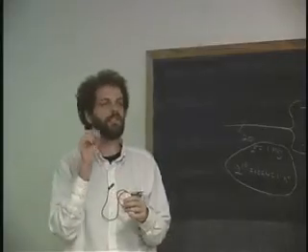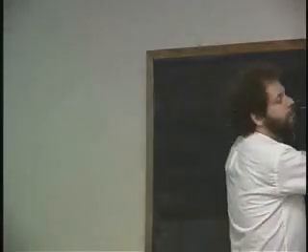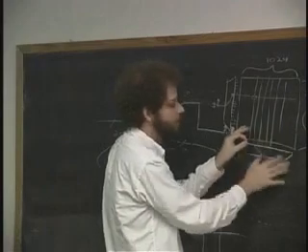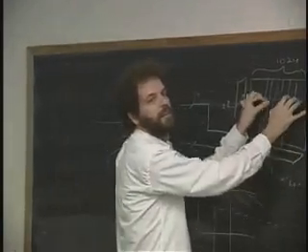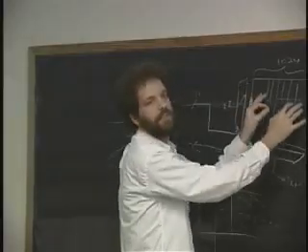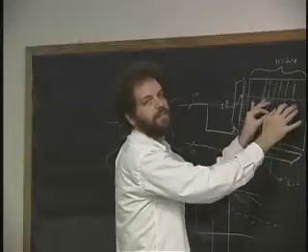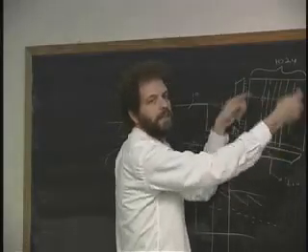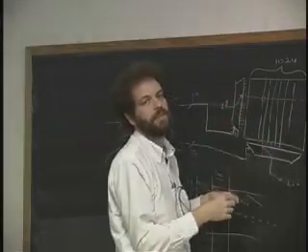It can actually send a signal to the chip which can massively, en masse, take a whole row of these bits, read them, don't do this thing of choosing one of them, restore them all, and write them all back. So it writes back, in this case, 1,000 at a time. It reads 1,000, restores 1,000, and writes back 1,000. And so all you need to make sure is that you go around and around here at least one circle every thousandth of a second, which is actually pretty easy to do.